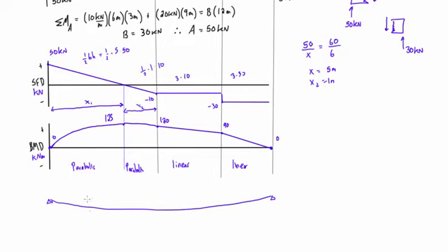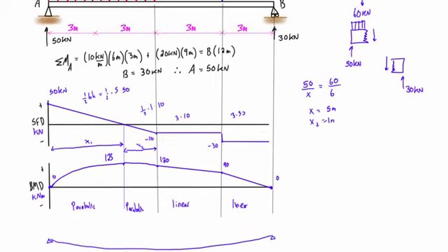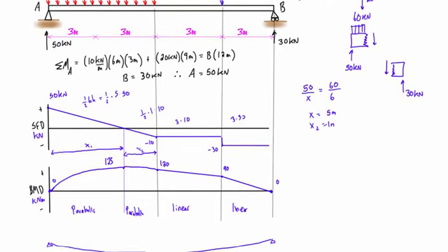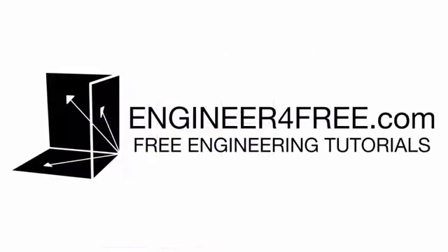It's probably sagging a little more to the left, but sometimes your teacher will just ask you to draw the general shape, and this would be sufficient to say, yeah, I get that when we load a beam with stuff pressing down on the top like this, it's going to sag down a little bit. Sometimes when we have overhanging beams it's a little less intuitive, but as long as you're able to use the bending moment diagram and some information that we get in more complicated problems, you can show that you understand the way that these beams are bending.